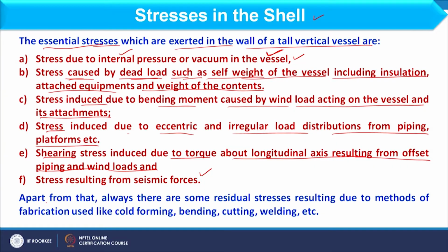However, if you design normal equipment such as a heat exchanger, reactor, etc., there we consider the stresses generated only due to pressure, but not other factors, because these factors are very minimal in that case. However, these factors are prominent when we consider the tall vessel. So, we should count each of these stresses.